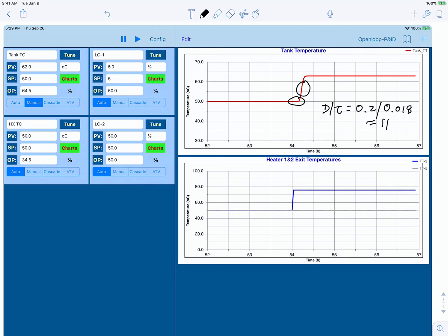Okay, that really concludes the analysis of the step tests, and we'll be able to use these pieces of information, namely the steady state gain, the dead time, and the time constant, and also throw in the dead time to time constant ratio as we analyze controller performance.